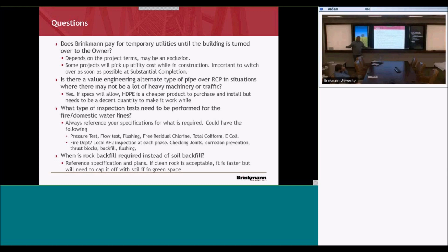You can usually get bigger sticks. As you get bigger with concrete pipe, the sticks usually get shorter. So you can cover long runs, but typically I think it's got to be quite a bit of quantity for it to be a good value. You can get away with PVC also. Based on the breakdown we got from some of our subs on the crossing down in Richmond Heights, they said it wasn't that much of a difference, but you have to think, if you're setting PVC sticks in the ground versus a concrete pipe in the ground, you should be able to move a little quicker with PVC.